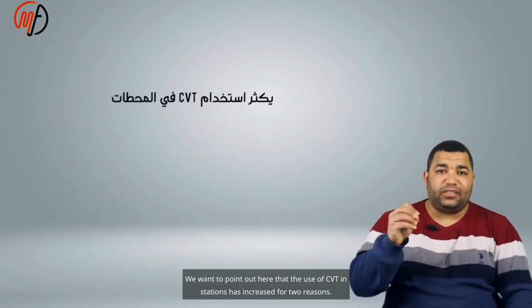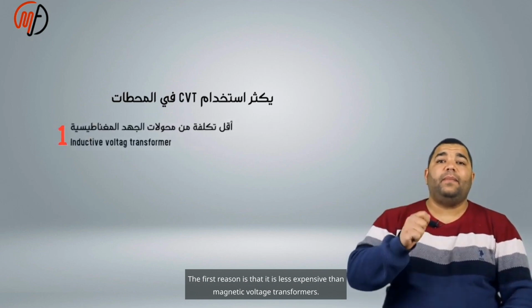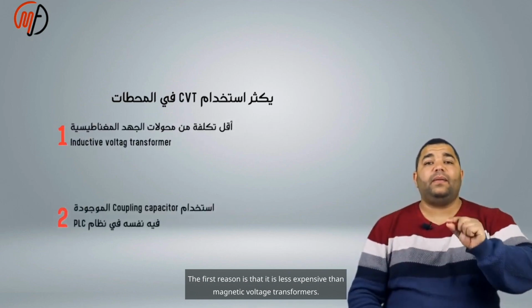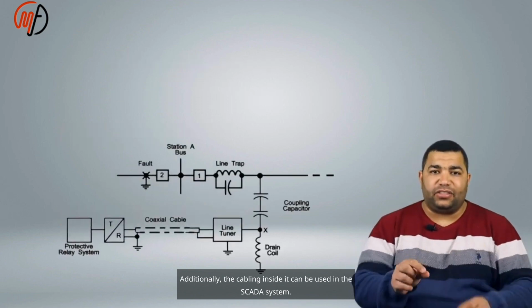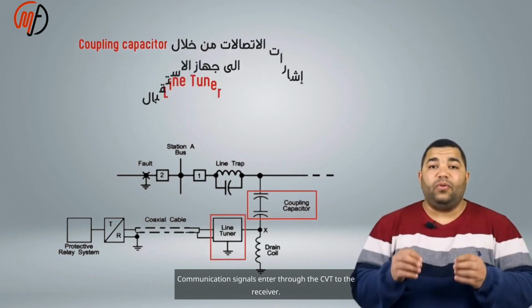We want to point out here that the use of CVT in stations has increased for 2 reasons. The first reason is that it is less expensive than magnetic voltage transformers. Additionally, the cabling inside it can be used in the SCADA system. Communication signals enter through the CVT to the receiver.